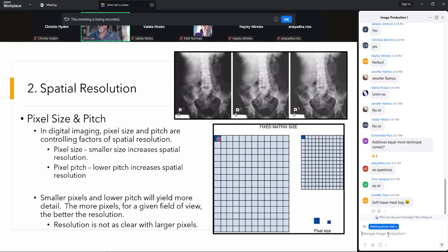But right now, it hasn't been solidified yet. But DEXEL is a really good way to describe these as opposed to pixel. What you see here in A, those squares of gray, that would be individual pixels that make up that digital image. But our cassettes, our flat panels, have detector elements in them. They have thin film transistors and storage capacitors as well as a bunch of wires. So another word other than pixel is in order here, but we'll go with pixel.